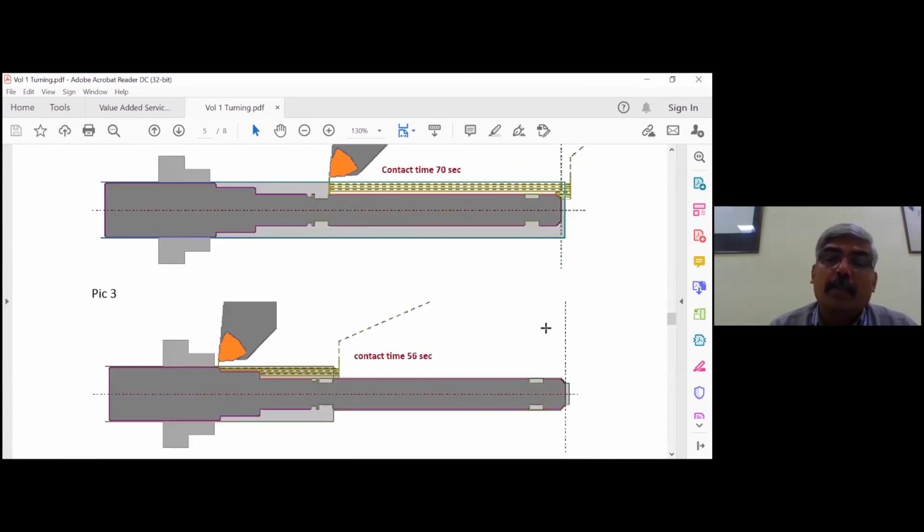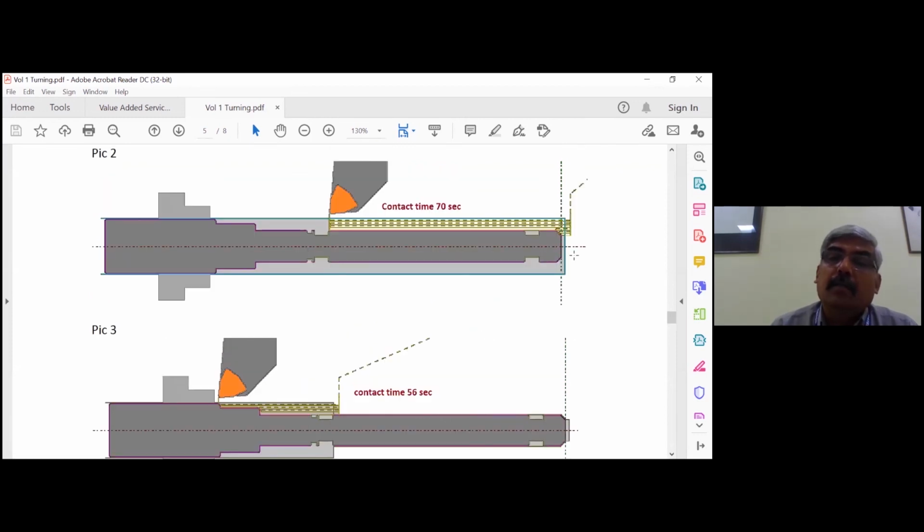Now in this case, what has happened when I did this, the first set of cutting from here to here, okay, it was going with maybe instead of 2 mm depth of cut, I go 1.5 mm depth of cut. Instead of 0.3 feed rate, I go 0.4 feed rate. No issues. The next cut, instead of 1.5, I go 1.8, but I will use 0.35 feed rate. Next, instead of 1.75, I will go 2.2 depth of cut. Then near the chuck, the machine is capable of taking 3 mm depth of cut or 3.5. I can take it, no issues for me.